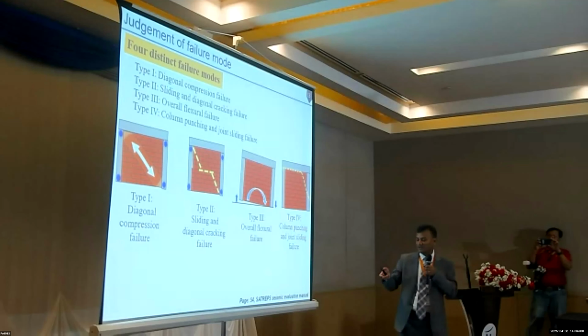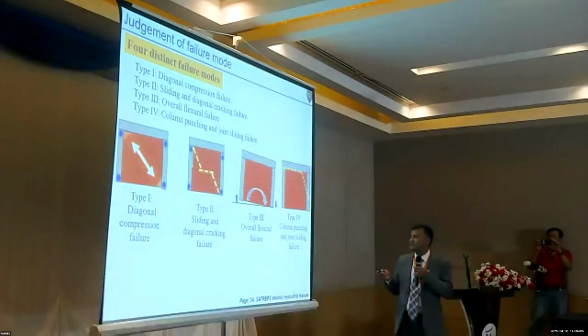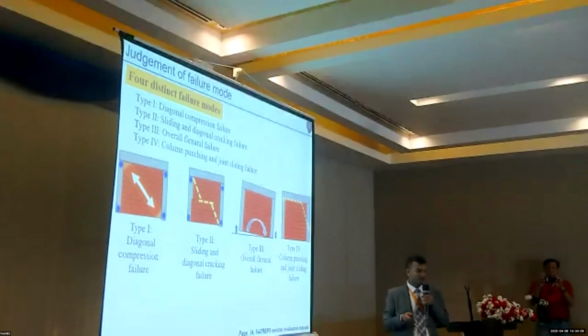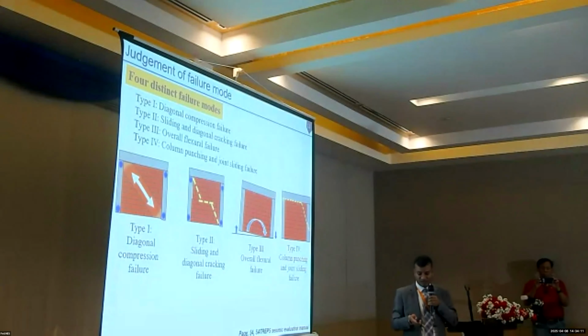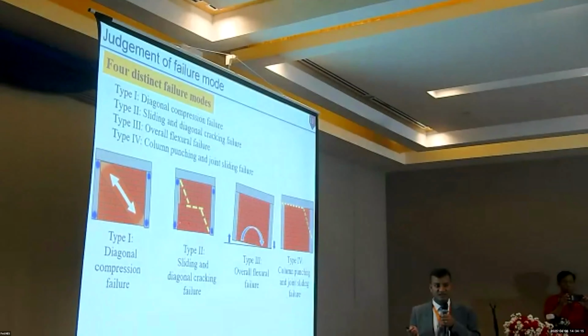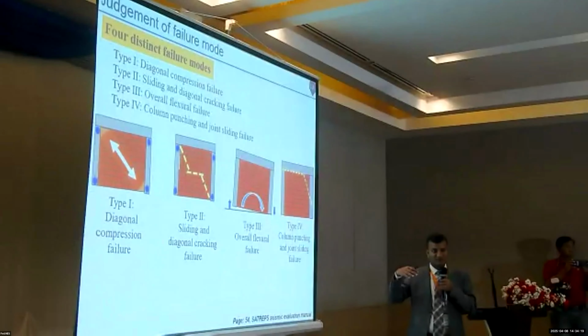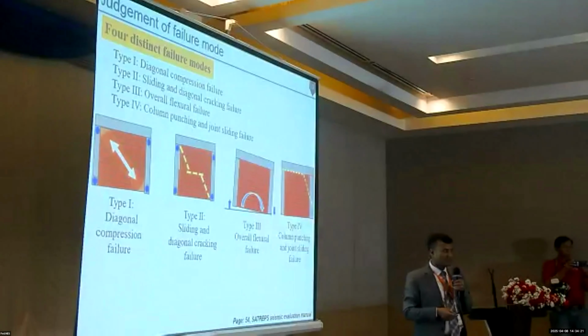For example, the column should be hinged here, but sometimes the column hinge is in another place. So that's why we are not taking advantage of this. But there is some advantage, of course, for this masonry infill. It increases the strength of the building, lateral strength especially. So that is the point.